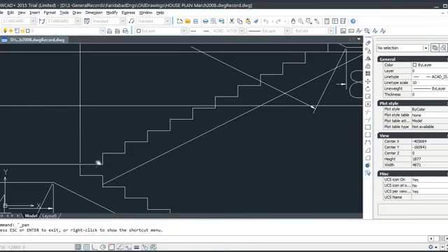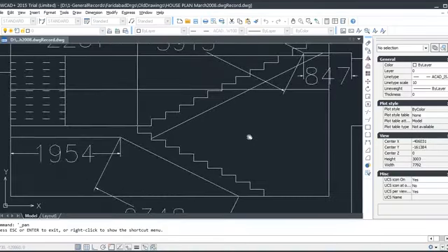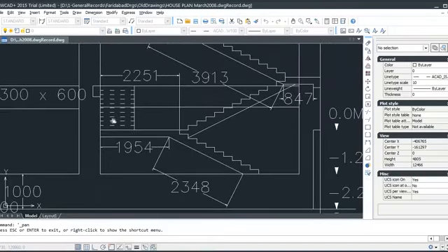Concrete should be monolithic. Some people cast this in concrete and put bricks here. That's completely wrong. This is a stair, and generally I am showing you the design is like this, from the center of this landing to the center of this column. We consider this span for loading on the stairs.